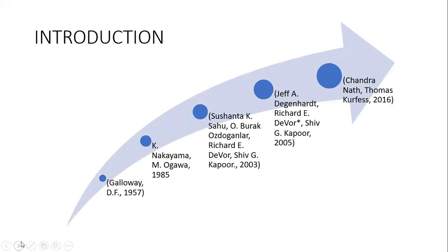One of the problems in conventional drilling is the evacuation of chips out of the drill hole. If the chip products in the drilling process cannot be evacuated, the chip will get caught in the drill bit so that it will rub against the drilling wall.